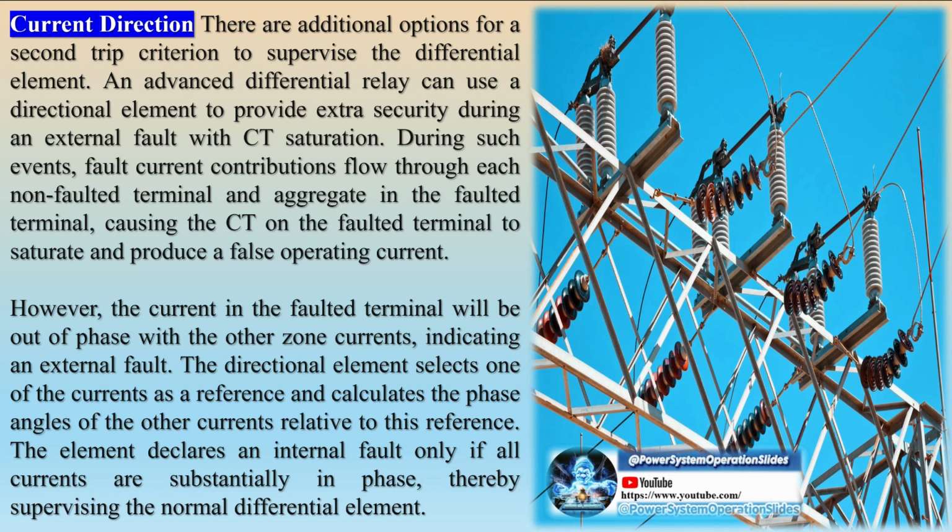Fiber optics, with their speed and EMI immunity, are ideal for arc flash detection systems. Optical detector unit includes an optical emitter and receiver, an optical sensor bare fiber loop, and fiber optic cable. The optical sensor collects flashlight and transfers it via fiber optic cable to the receiver, which converts the optical signal to an electrical signal for the control system.